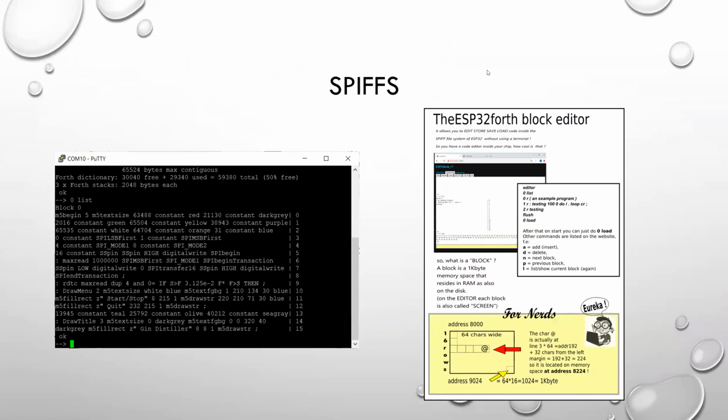Right. Okay. And in addition, in the project, because this will end up having to be a standalone function that we could eventually just simply turn on the machine, it's running Forth underneath, and we just want to set it going. We shall make use of the blocks of the block editor and the SPI FFS to store all our functions. Later on I'll be adding it into the auto exec so that we load block 0 and later on block 1 as well.